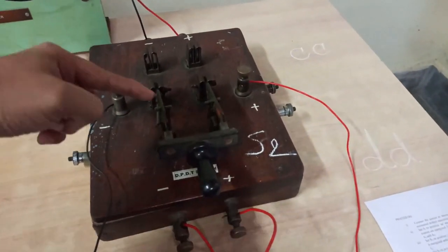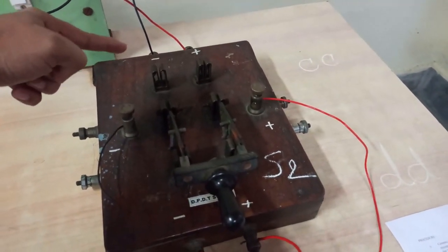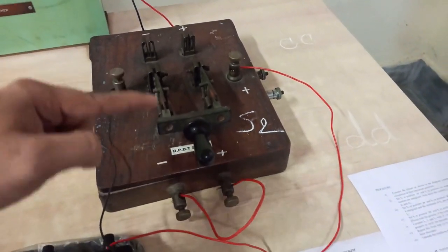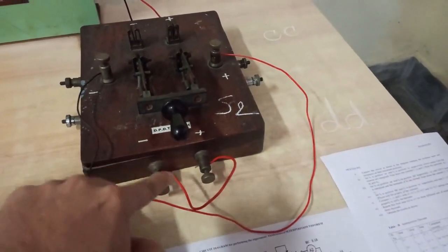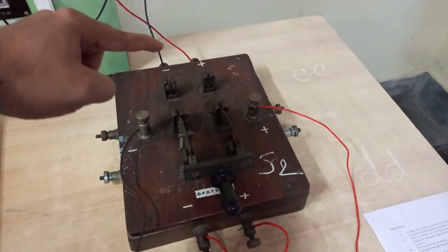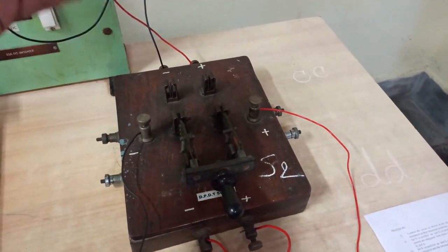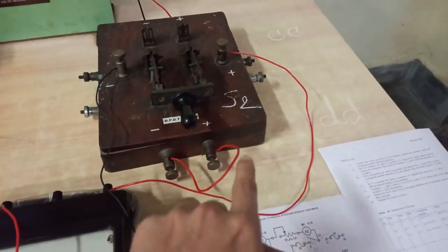So, initially this was connected to that side and 110 volt supply was connected. Now, we have shifted it to this side. So, it is connected to a short circuit path. Basically it is not the case that we are short circuiting a voltage supply. We are just removing the voltage supply, and instead of that voltage supply we are placing a short across it.